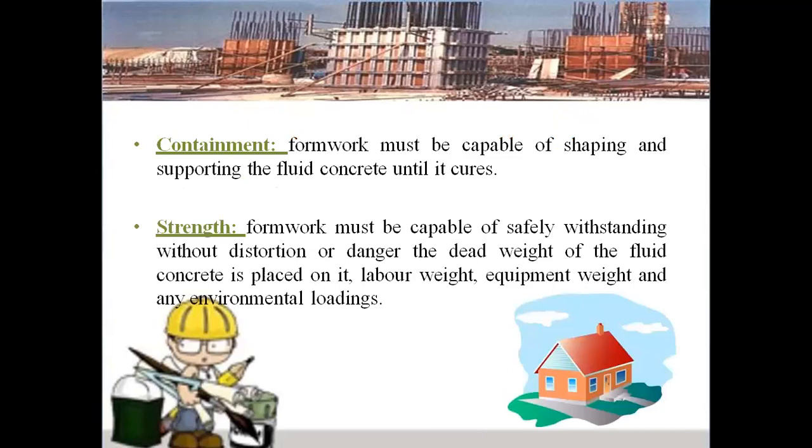So the formwork must be capable of shaping and supporting the fluid concrete until it cures, until it gets sufficient strength to withstand its own self weight, so the formwork must contain the fluid concrete which we pour into it.